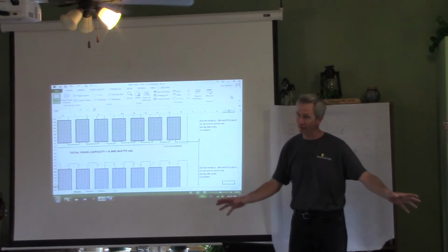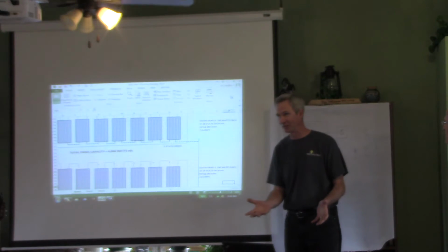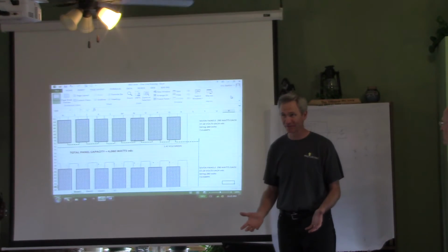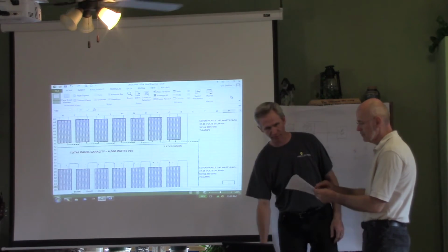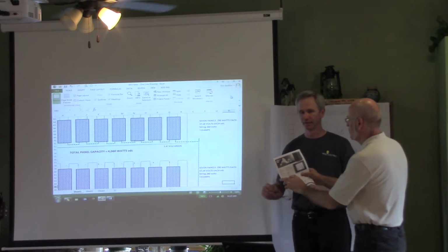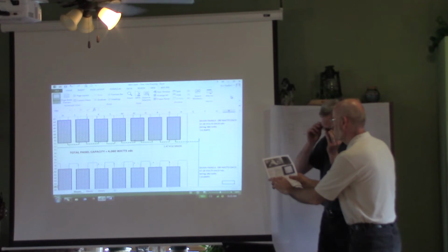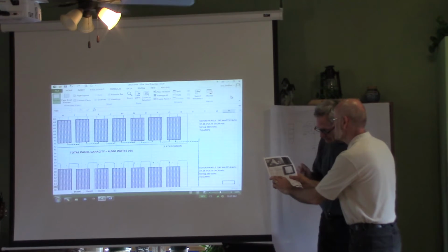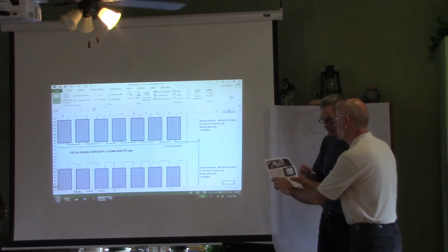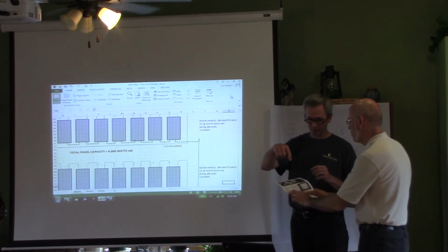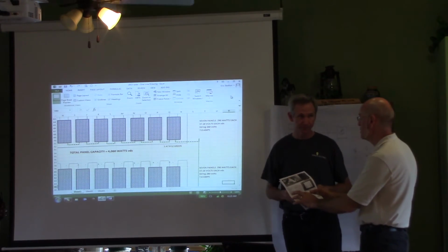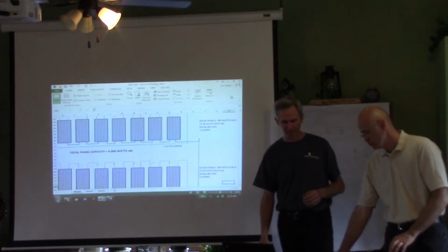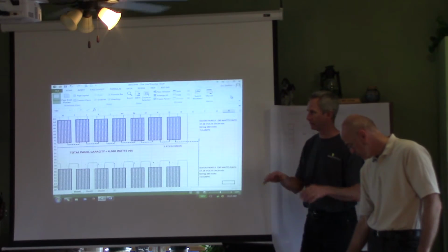But then he says, well, now wait a minute. We got another element here too. What are going to be the amps? Again, we just talked about amps, right? We talked about the capacity. So we look at the solar panel specs again. The 7.8, current at P max. 7.8 underneath, right? On our spec sheet for the universal solar. Now remember, that's at 70 degrees, so at perfect temperature, our average temperature.